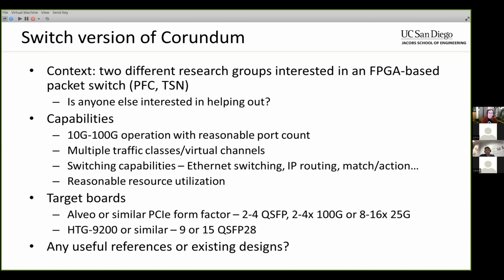So, for example, if you want to do some layer 3 matching, then maybe it's enough for your experiment to just use the lowest 4 bits of the IP address. Then the lookup is pretty straightforward. You can directly implement it in LUTs, and you don't have to rely on hashing and whatnot. That might end up being pretty complex, especially if you want to do it in a known latency. So I guess that's another way of reducing complexity without sacrificing functionality. But it depends on the experiments, right? So I don't know.